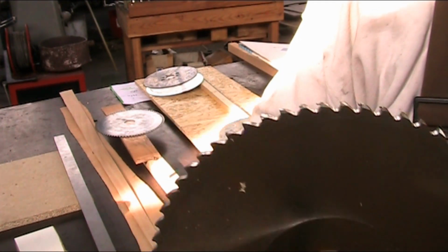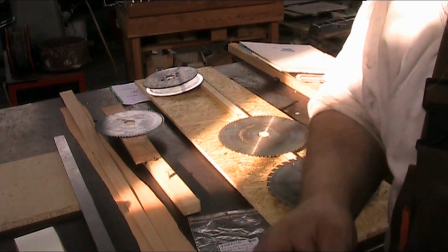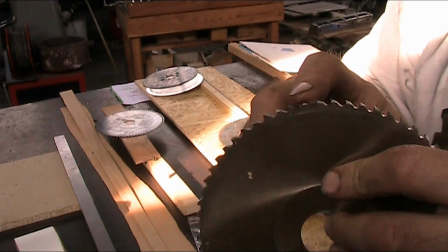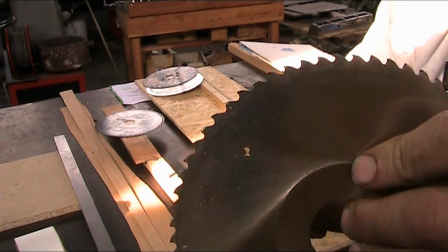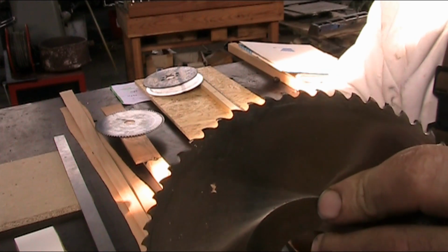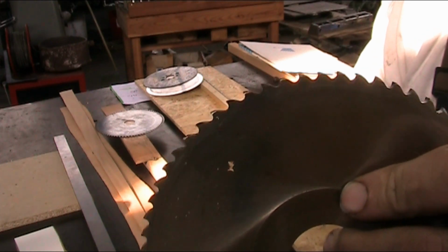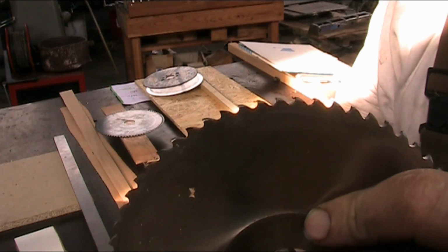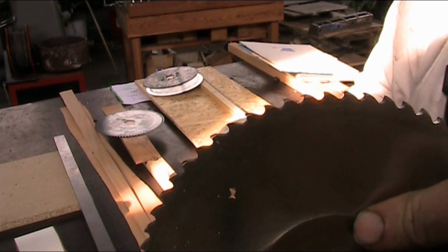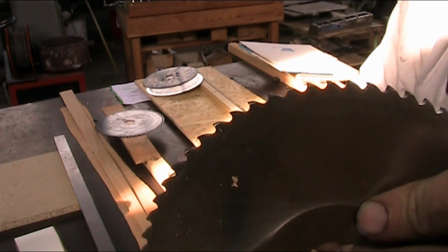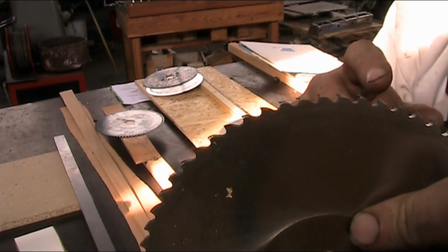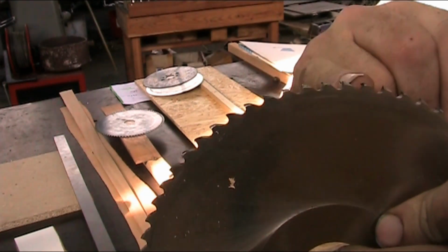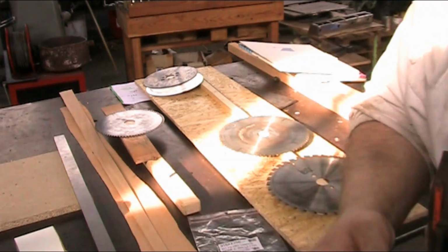It just means the overall distance between the teeth. Now, as you notice here, you've got a pretty close tooth count, a lot of close distance between the teeth, and so this is considered a PV. Although you could, for the metalworking aspect of it, call this a PU because of the shape of the gullet.